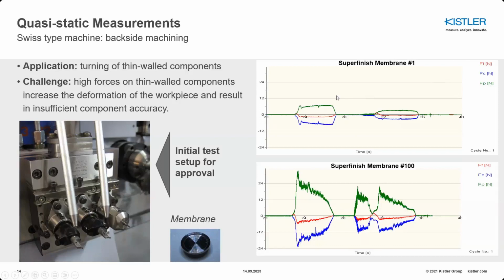And this is the first part, how the forces look, and then after 100 parts you are really reaching certain limits, and after that level you are deforming your material. So even if the tool is not too worn, we know that that level should not be overshot, right? So we should not pass that level.